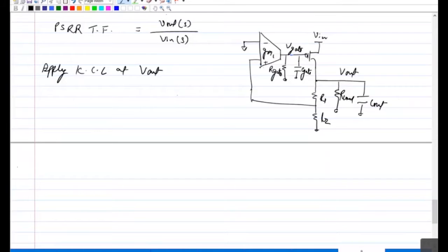Okay, so there'll be no current from the PMOS? Sir, there is one gm2 current and the r0 of the same PMOS. Yeah, basically the current from PMOS will get divided into these 3 branches. So you have to consider the current from PMOS when you're applying the KCL. Actually, I thought of the current going out of that node, and I didn't consider the current coming in.